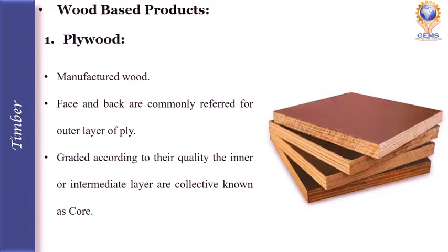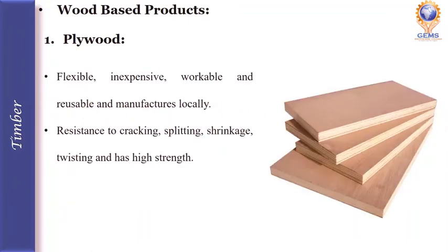The inner or intermediate layers are collectively known as core. Ply is flexible, inexpensive, workable and reusable, and we can manufacture it locally. These plywoods resist cracking, splitting, shrinkage and twisting, and have high strength.